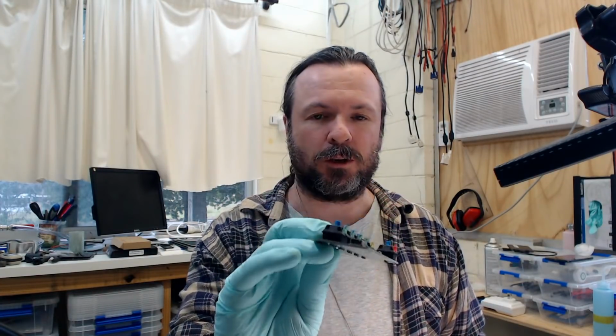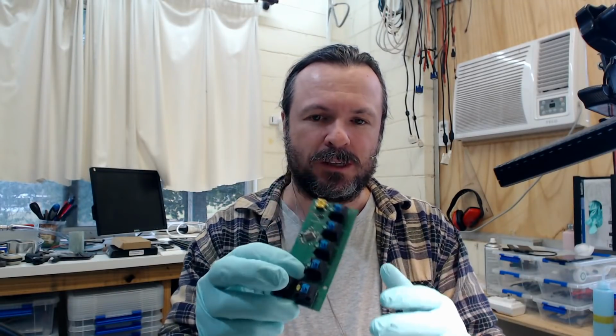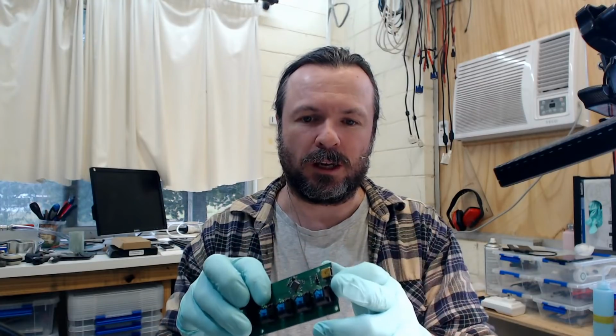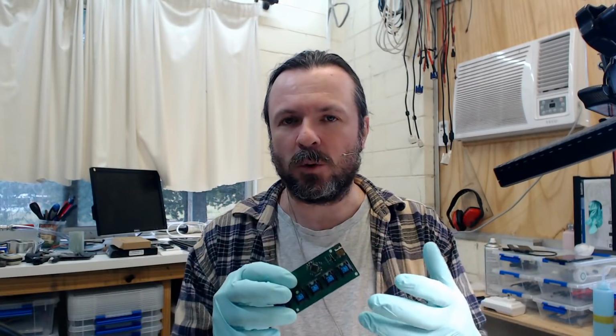Sometimes it's more convenient to just be able to switch a scene by pointing to the camera that you want. That would be nice. Previously I had one of these units which I made up. It's just a simple 6-way switch to pick the different scenes. The microcontroller connected up to the USB would generate a keyboard combo, the same as pressing a keyboard combo, and OBS would react to that and change the scene.